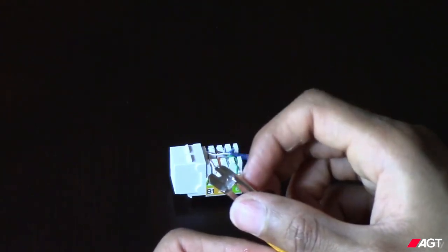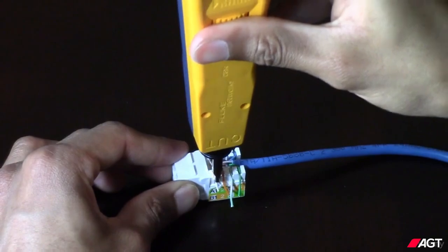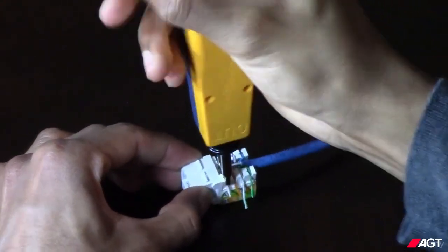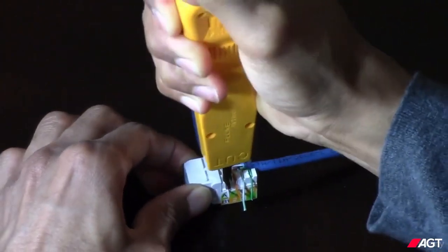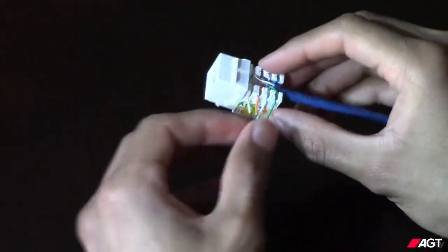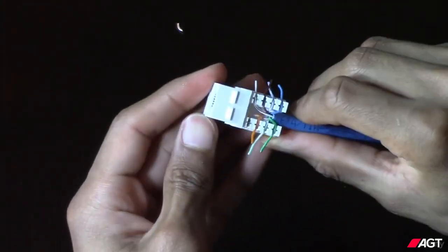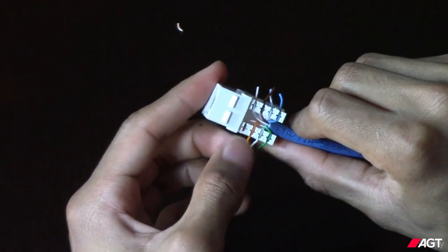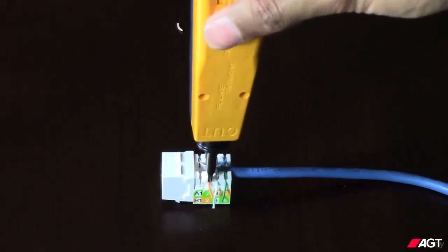When you punch down, you'll want to make sure the cutter side is always facing outward. Take the blade and insert it into the first slot like this. Then, depending on the tool you have, you might want to be standing up. Push gently but precisely. Once you've pushed in a little bit, it'll hammer down and simultaneously secure and cut the wire at the same time. I'm using a lower impact force, so it might not fully cut all the wires every time, but it's okay, you can usually just flick it off. Now we've got to do the rest.